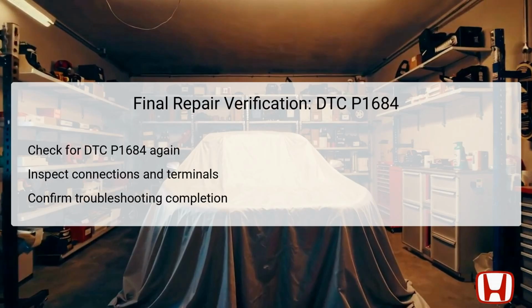In the final repair verification step, check once more for the DTC P1684 using the HDS. If the code reappears, it indicates that the problem persists, suggesting a potential issue with the throttle body connections or the wiring harness leading to the engine control module, ECM. Inspect all connections and terminals at both the throttle body and the ECM for signs of corrosion, damage, or looseness. These faulty connections can lead to intermittent signals that trigger DTCs.